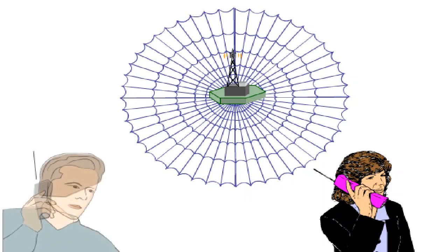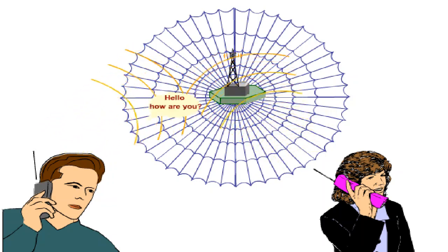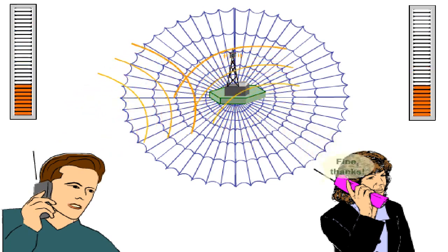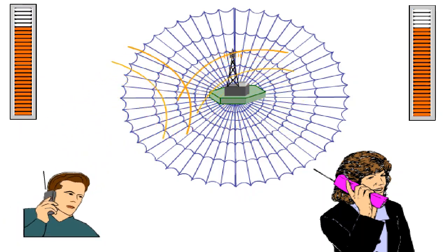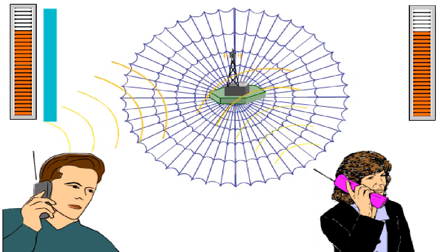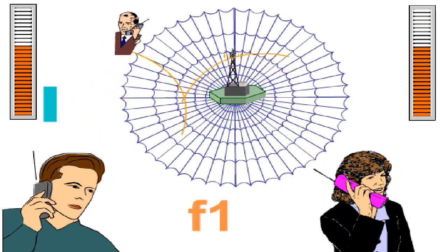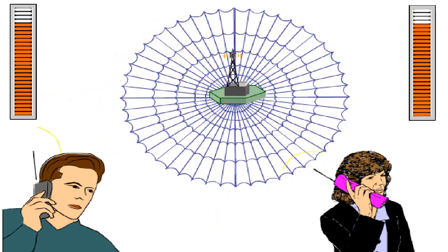In GSM, all voice signals are transmitted the same way and in a continuous data stream. The channel is occupied even during silence intervals. This has two fundamental disadvantages. Firstly, since the mobile station must send for the whole duration of the call, transmitting power is used even in silence intervals. That means when the subscriber is only listening. This wastes the mobile station's battery power. Secondly, other subscribers using the same frequency in distant cells could be disturbed more than necessary.